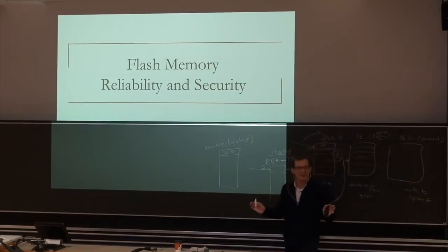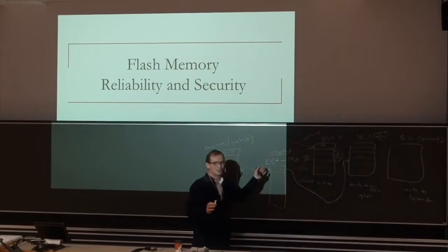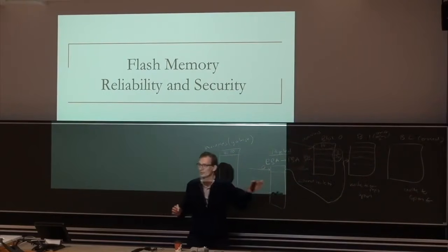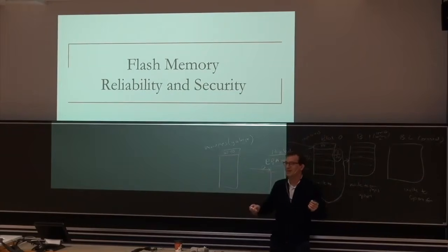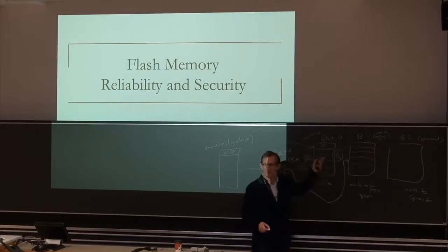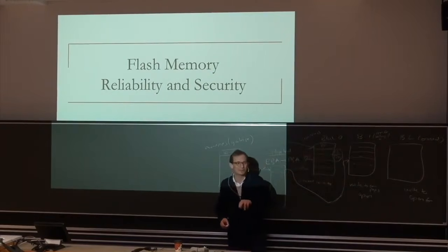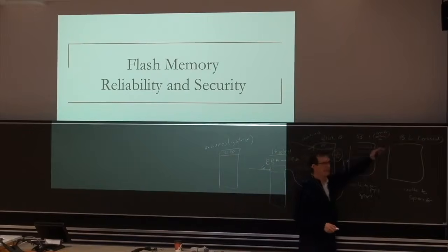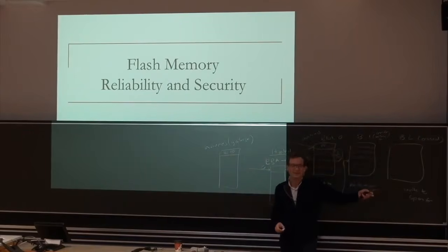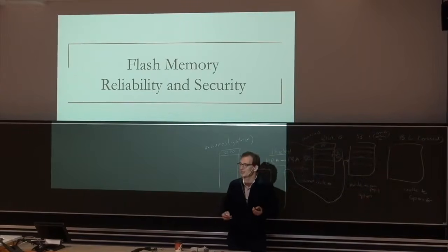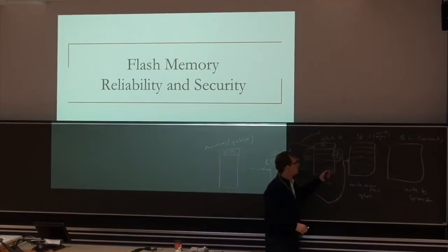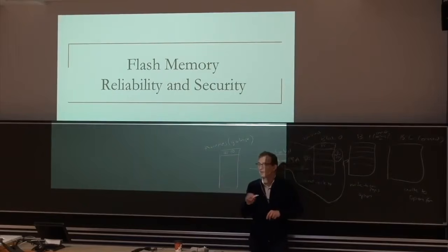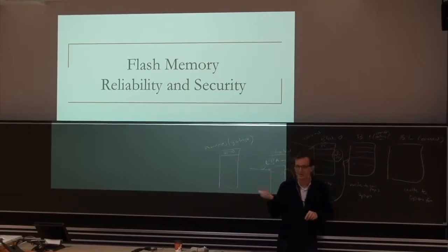So that sounds good. Of course, it's not that simple because of other issues with the device, right? The device has another issue which is called wear out. So if you keep writing to only a single block, that may be good for garbage collection purposes, but that's actually terrible for wear out purposes because you keep wearing out the same block all the time, right? So you want to balance that. You need to do wear leveling across the blocks or across the pages to ensure that you distribute the writes. This is the endurance problem that we discussed.